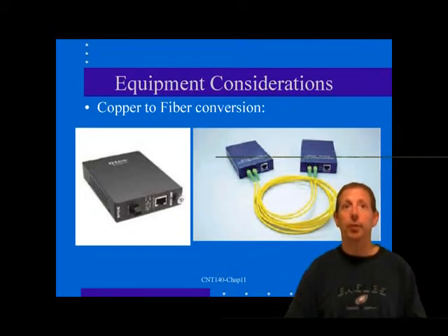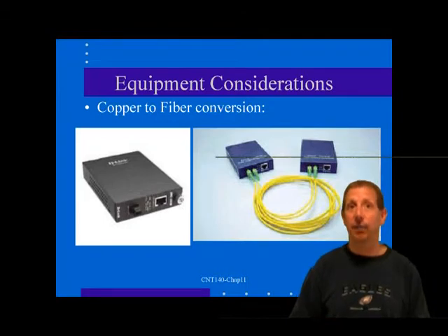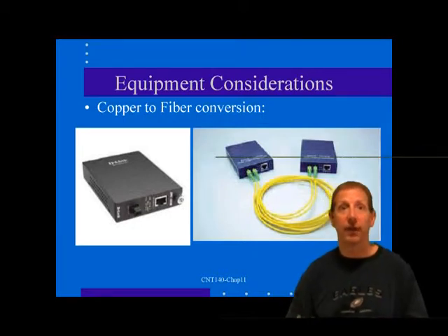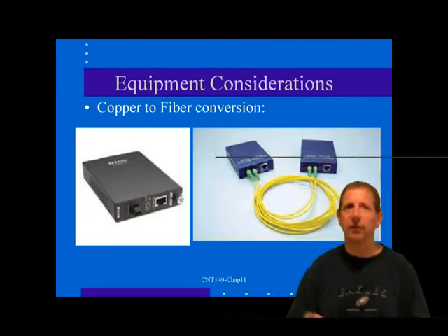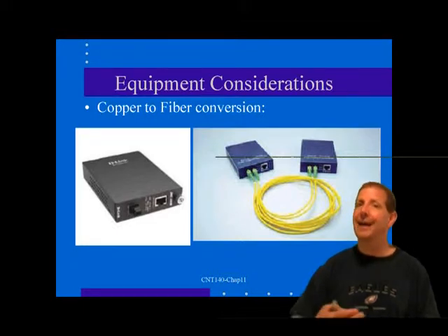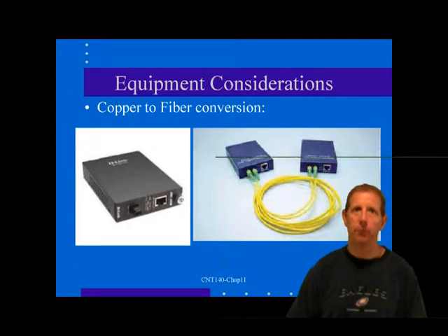Mode converters typically put a pair of wide bandwidth transceivers back to back in a box. One set of optics is single mode and the other is multi-mode. In between the interfaces is the proper electronics to repeat the signal to the opposite interface. For this reason, you can expect fiber mode converters to cost several times more than a simple fiber to copper converter. Now, let's look at some of our installation practices.